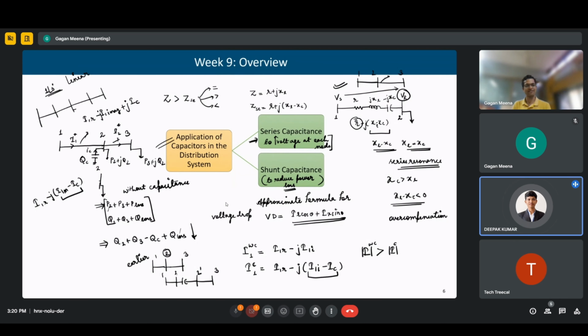So we cannot insert it in an overhead line directly; we have to make a substation, because it is in series. If in an existing line I want to add it, then I need to break the line first, then add the series capacitor, and then connect it again. But sir, with such a large, heavy voltage, can they stay with that?